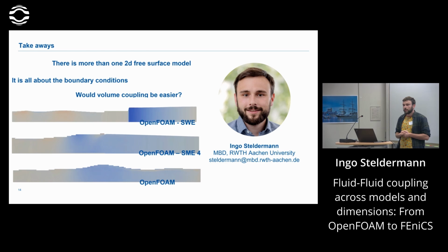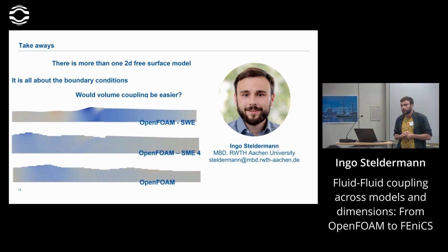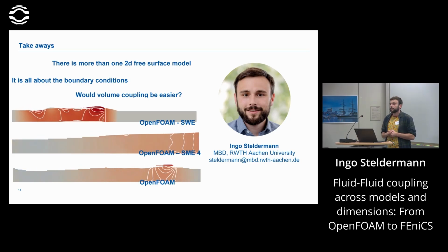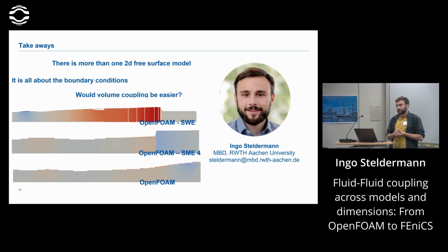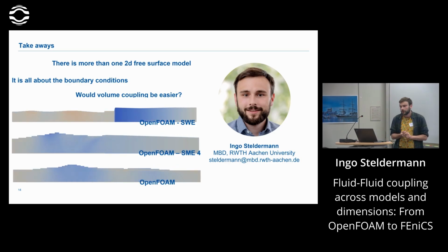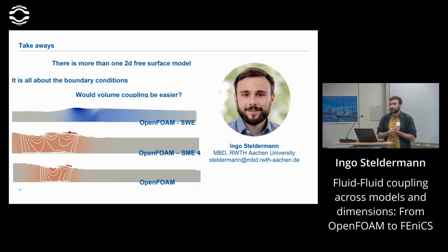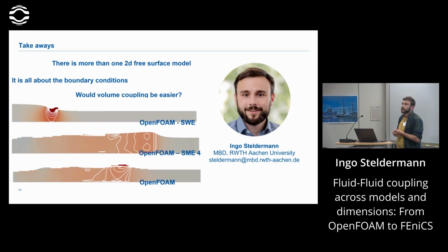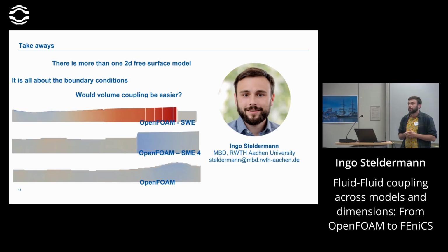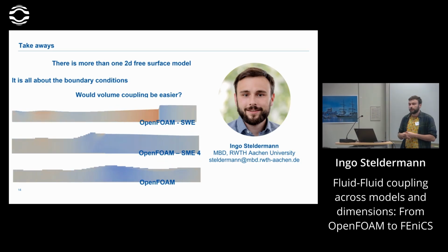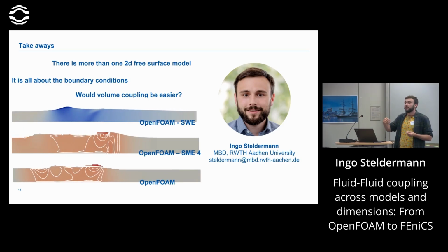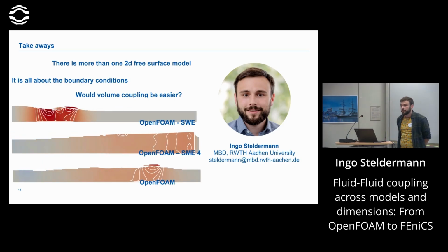I was just going to come to that. I only know this from the granular community. They use shallow water models all the time, but when they do this, they introduce a shape factor, which is the difference between the average of the square velocity and the average velocity squared. That extra degree of freedom allows you to conserve mass and momentum separately, because it introduces an extra parameter. But the shape factor is built on, for example, the assumption of a log profile, so it only holds for this one. I agree, that's where we are coming from. This enforces mass and momentum conservation for a given profile.